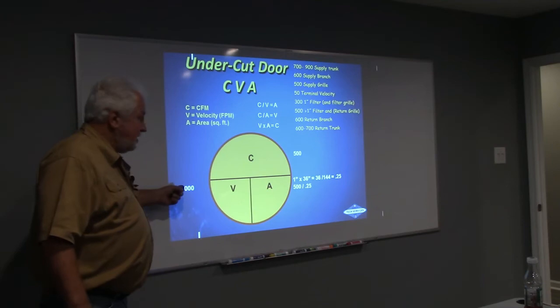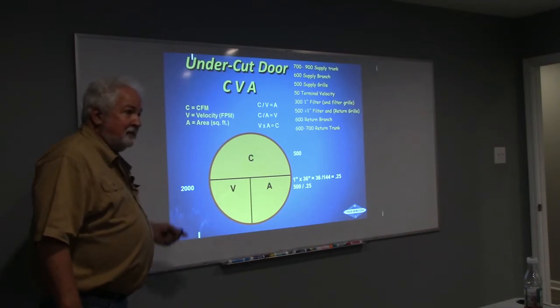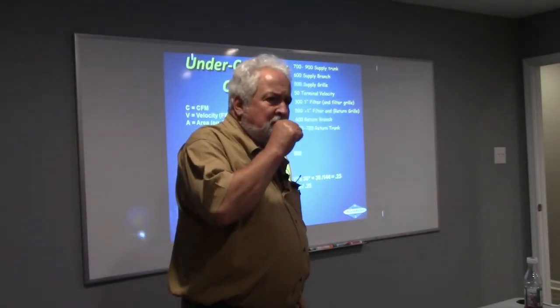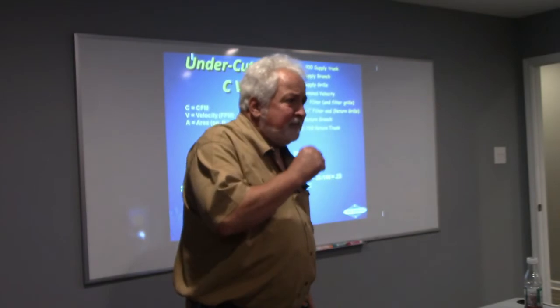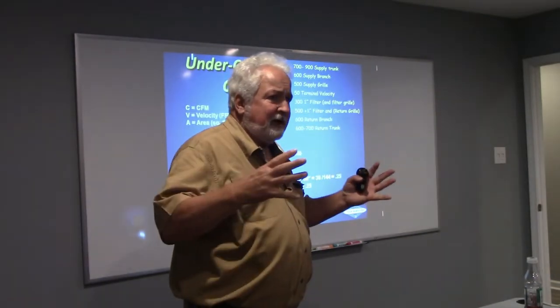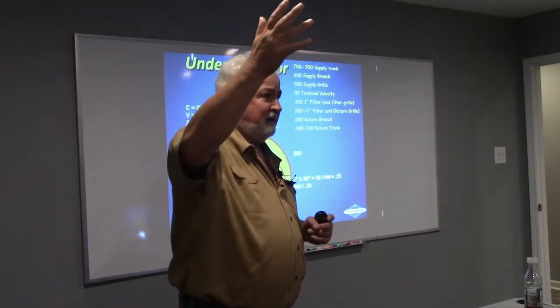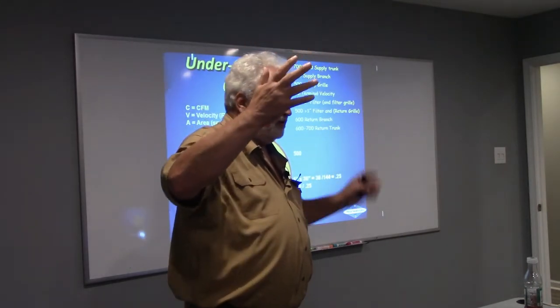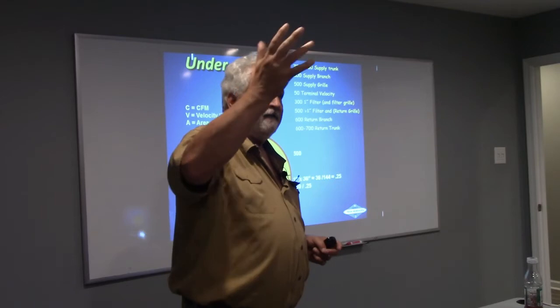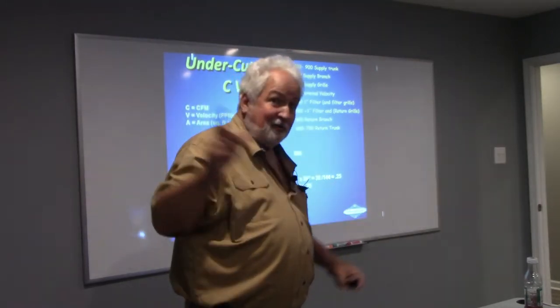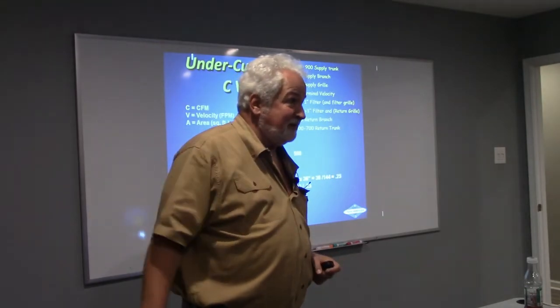All right, so not good, right? What happens to your airflow out of your grill when your room pressure goes like that? I don't know, let's see. Blow into a Coke bottle. What happened to the CFM when I blew into a static room? Stop. So if you do feel air coming out of there, and that door is closed, what air I feel coming out must be going out, either going under that door or going through every crack and crevice. Does that make sense?